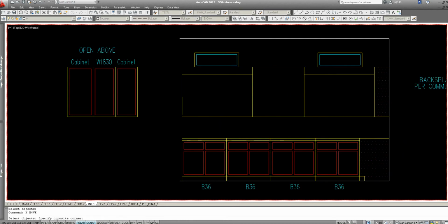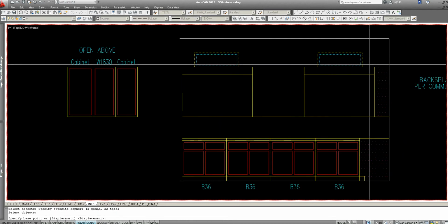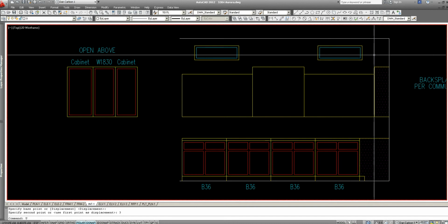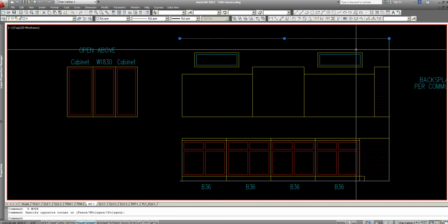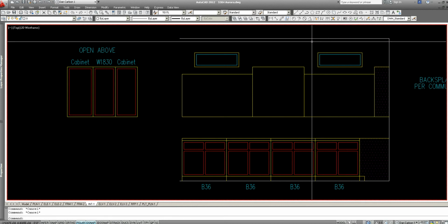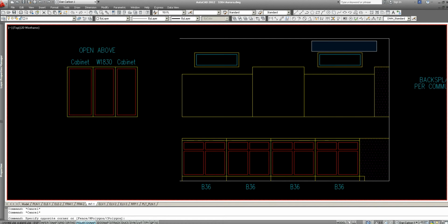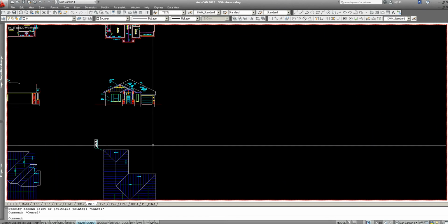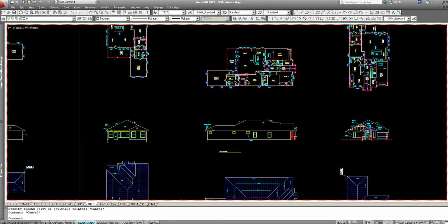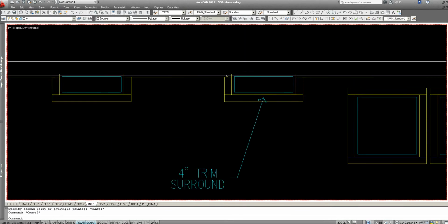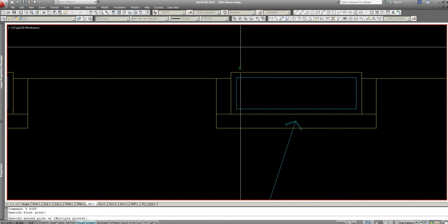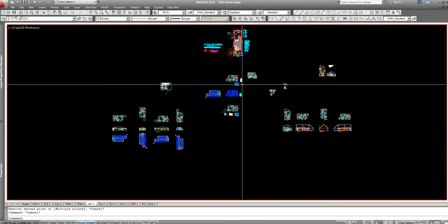Now you might say, well, why don't we just put these windows a little higher? Why wouldn't they go up here? Or even up here? Well, the reason is our roof plate is right here. And we need to have at least a good 10 to 12 inches above it for our header to support the rafters. And then also our overhangs come down and almost block the window. This is the bottom edge of our overhang, and you can see the window's only below it by about an inch or two. That's why we can't raise the window any higher than this,